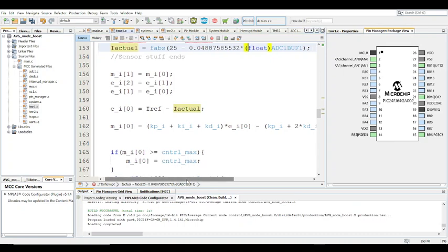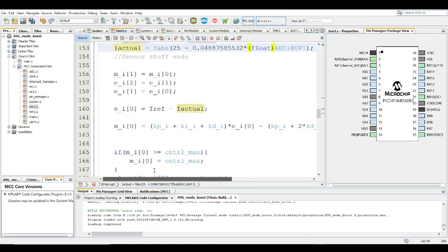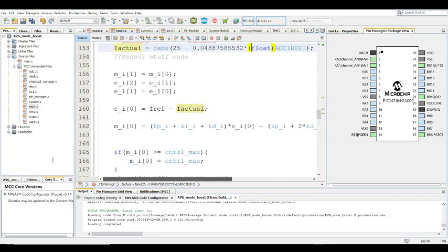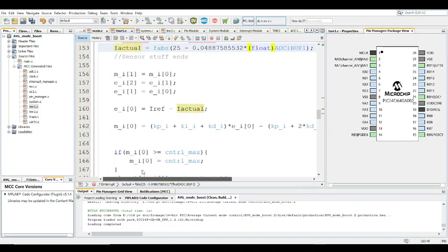So essentially I'm using a velocity form PID controller because it works. I find it works better for control of DC-DC converters. It works much better than the position form. The normal form, the familiar form, is the position form. Widely used in a variety of applications, but I find for this one specifically, for me anyway, this works much better.